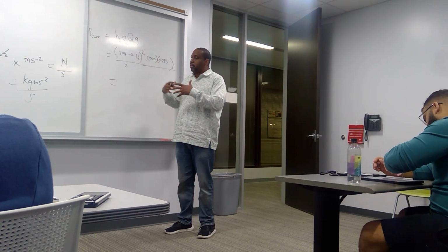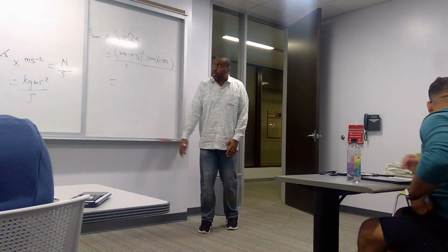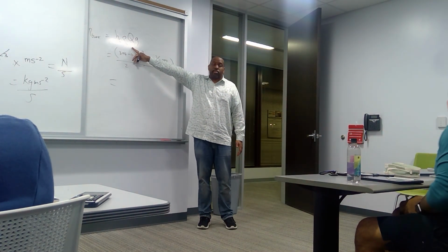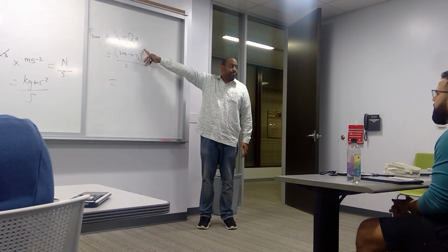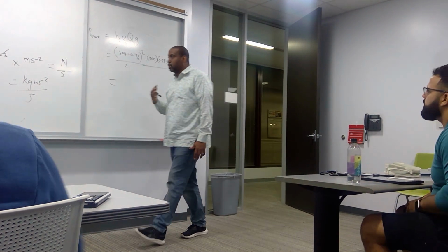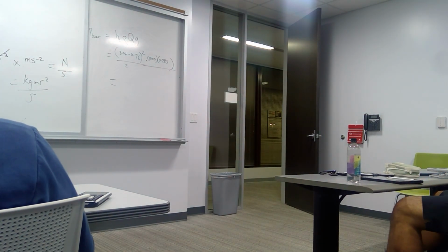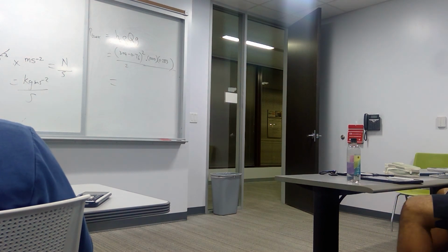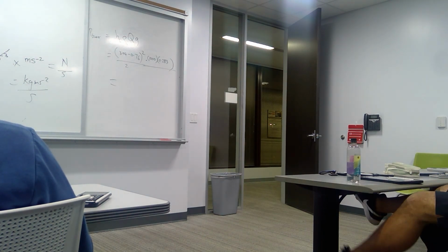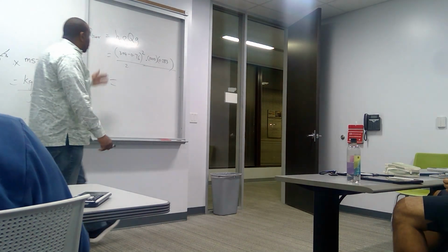We find all the loss, the total head loss, and we multiply by rho Q G to find the power needed to push that water through. We calculated that using our units. So, that's our power.